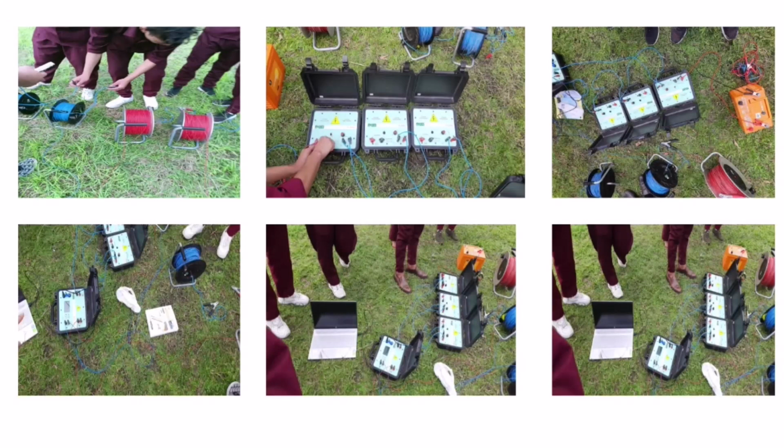ERT is a geophysical technique for imaging subsurface structures from electrical resistivity measurements made at the surface using electrodes. It is an advanced geophysics method used to determine the subsurface resistivity distribution by making measurements on the ground surface. ERT measures resistivity, which is measured in ohm meter, and it is the mathematical inverse of conductivity. Resistivity measurements can be made with either an alternating current or direct current.